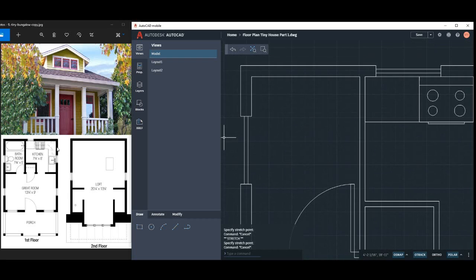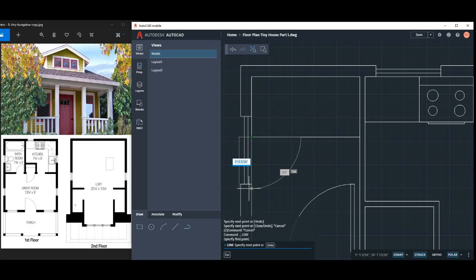Okay, so first thing, I'm taking a look here. I can see the tub. There's a line that goes right across these walls. I know that the typical width of a tub is 32 inches. So I'm going to click here, shoot down this way, type 32 inches and shoot that across. I'm also going to do the same thing I did with the sink on the other side there, where I had to extend the sill, like I just did there.